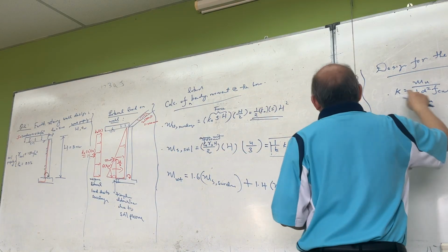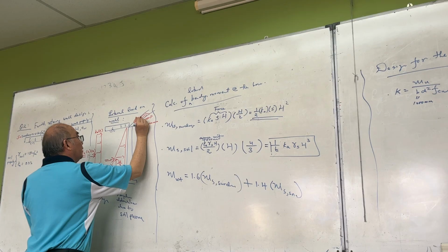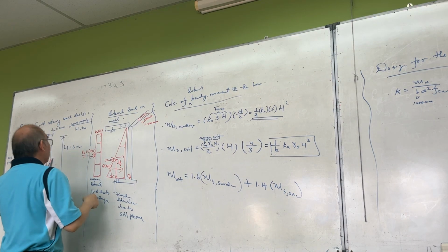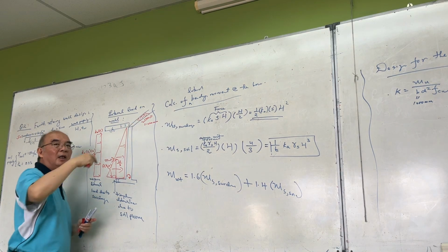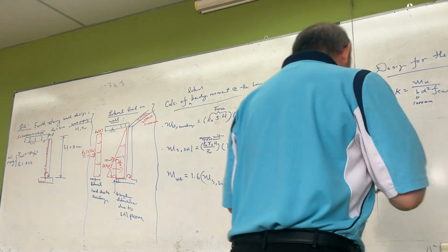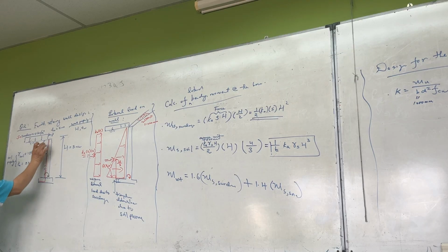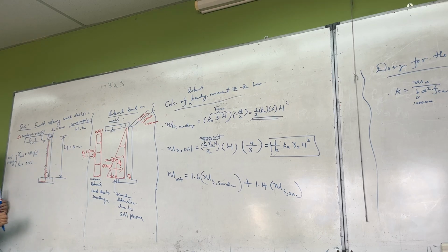For example, this B here, this is my reinforcement at the back face, right? So let's say the thickness is 200, the D might be 150, but nonetheless I'll give it to you. Understand? Okay? So this is the D. This is the thickness of the concrete. D is only measured up to the rebar. Understand? Okay? D is called the effective